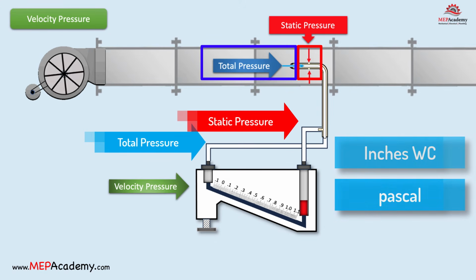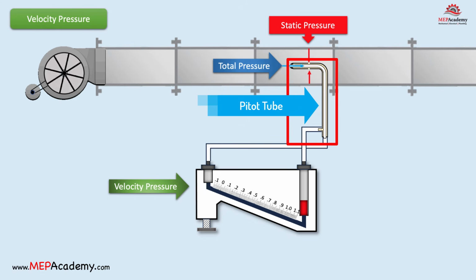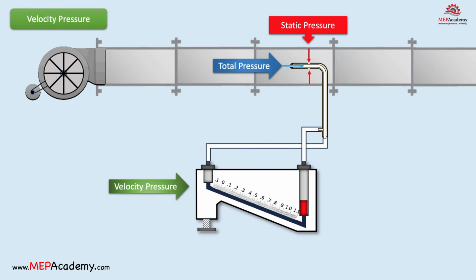Direct measurement of velocity pressure is not done. Instead, the most straightforward method to ascertain the airflow velocity is by assessing the velocity pressure within the duct using a pitot tube assembly linked to a differential pressure sensor comprising both a static pressure probe and a total pressure probe. The pitot tube can be inserted into the airflow to measure both static and dynamic pressures. The dynamic pressure measured by the pitot tube represents the velocity pressure.